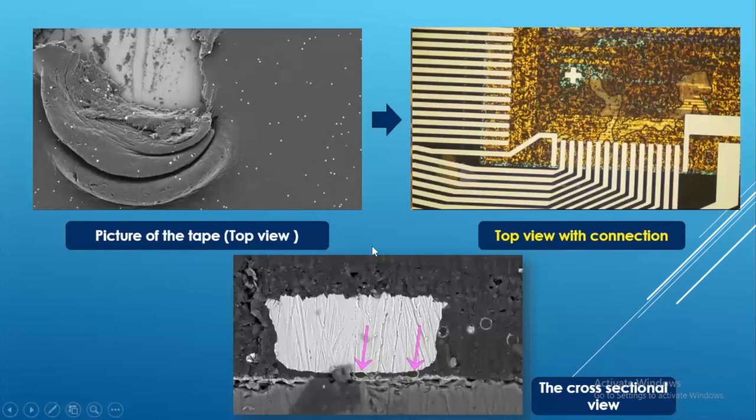So this was the whole picture of how we are connecting our ribbon from the circuit board to the LCD panel with a simple method, the anisotropic conducting tape, in which conduction happens only in the Z direction, and in the XY plane there is nothing happening. It is very easy to use commercially, because you simply cut and paste the tape on the LCD panel.